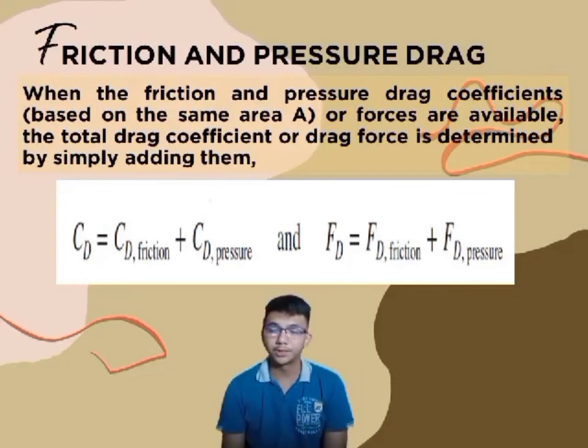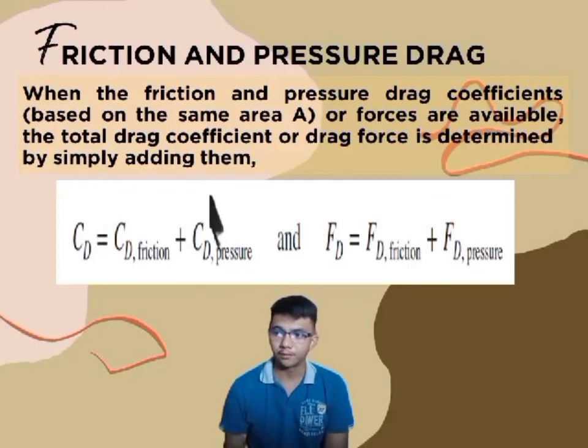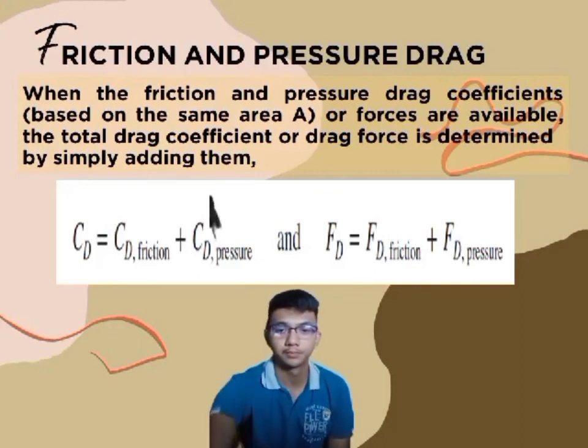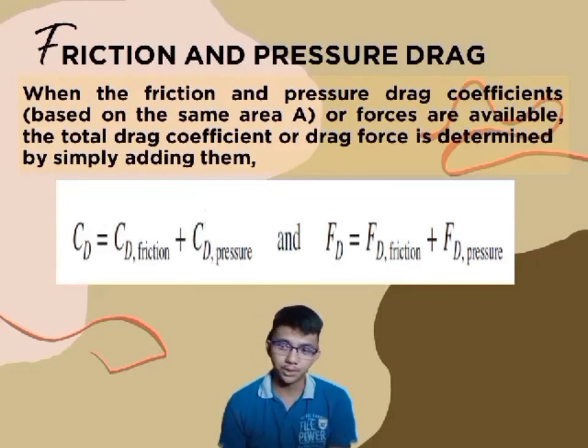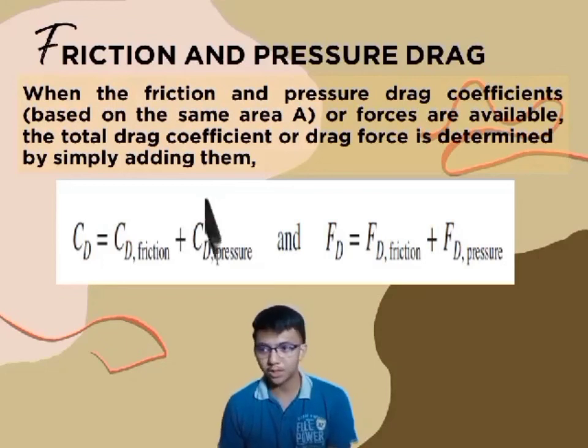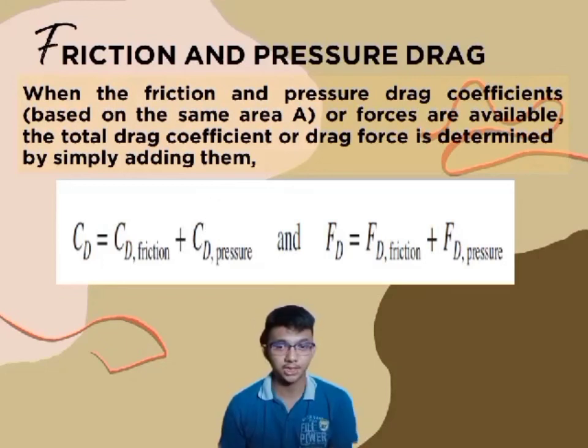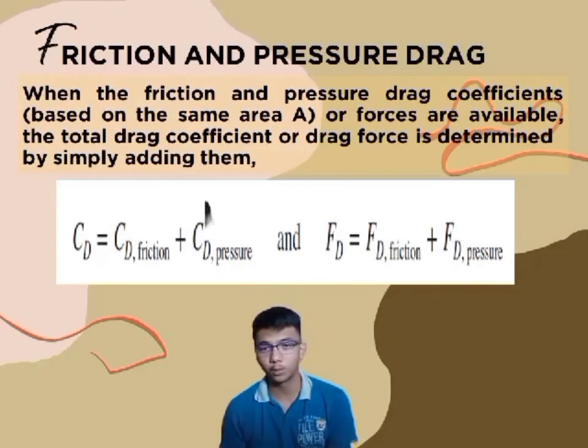Reynolds number is inversely proportional to the viscosity of the fluid. Therefore, the contribution of friction drag to the total drag for blunt bodies is less at higher Reynolds number and may be negligible at very high Reynolds number. You may be curious, what is Reynolds number? Reynolds number is basically the ratio of inertial forces to viscous forces within a fluid which is subjected to relative internal movement due to different fluid velocities.